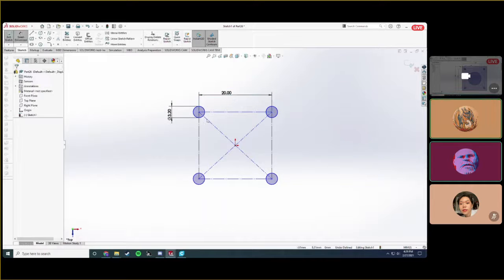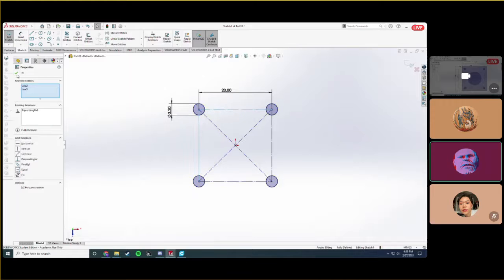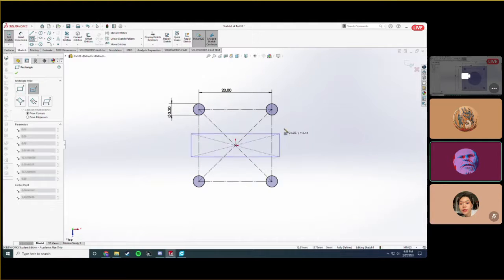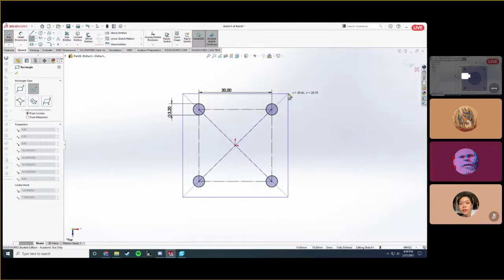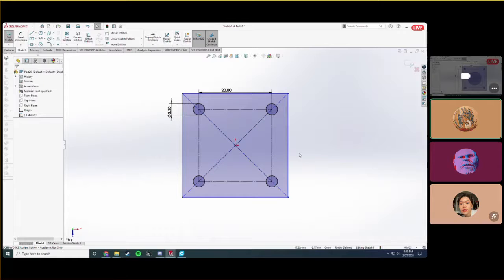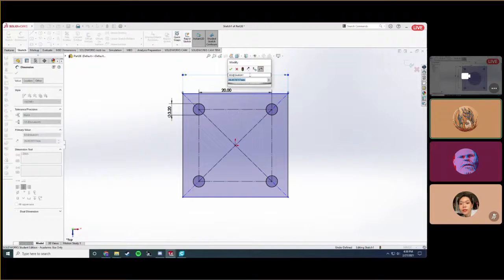Yeah, even with sheet metal parts, you should make things a little bit bigger for holes. It's not just 3D printed parts that need to be toleranced. You don't want it to be exactly, just a little too small and then you have to hand drill out the holes so your screws fit. That would be annoying. Okay, and then this can be arbitrary, I guess, because we don't have any specific requirements.